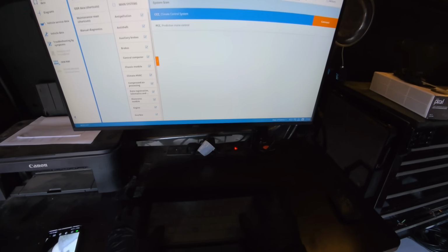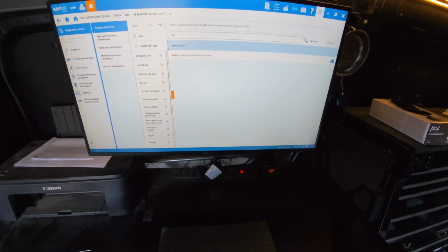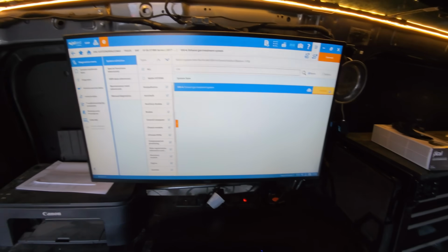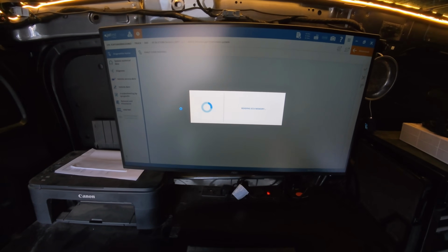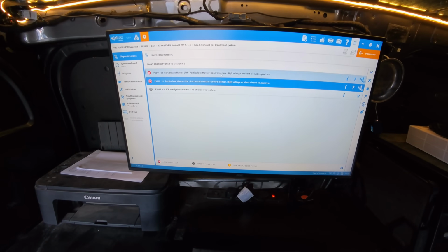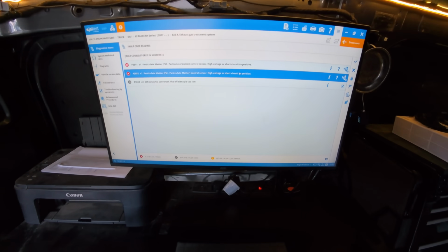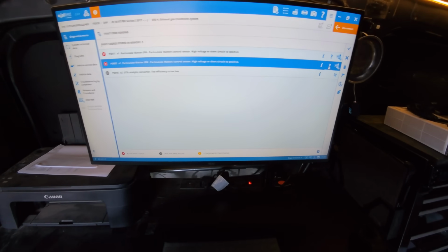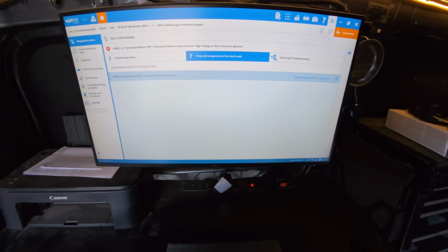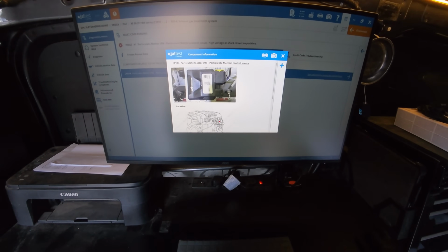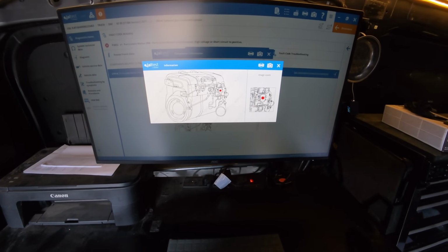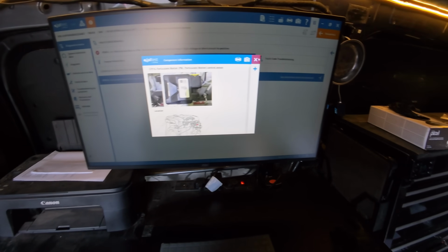He had an exhaust system warning, so we'll have a look at EAS now. We'll go to fault code reading. Our old friend, particulate matter sensor, voltage too high or short circuit to positive. I can tell you now that will need a new sensor. There we go, it just sits on the exhaust there. I haven't got one of them. The customer can get one of them.